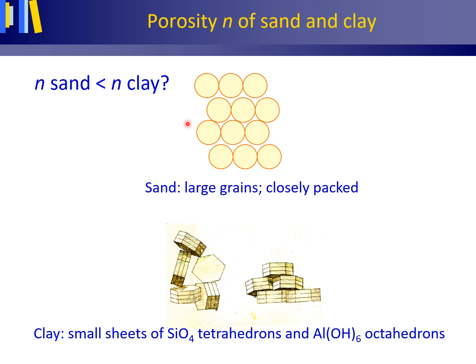Sand has a granular structure with much water held in pores between the grains by capillary forces, whereas clay minerals have a laminated structure as shown here. Due to their mineral structure, small sheets of silicon oxide tetrahedrons and aluminium hydroxyl octahedrons, clay minerals are negatively charged at their surface. The mineral's negative charge is neutralized by cations, positively charged ions, such as sodium Na+ and calcium Ca2+, in the soil water.